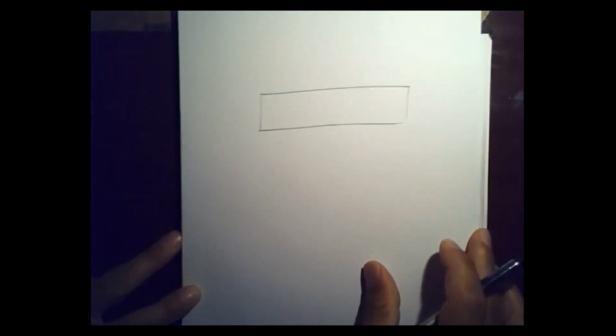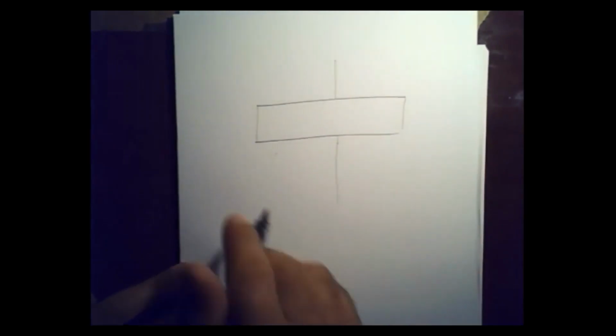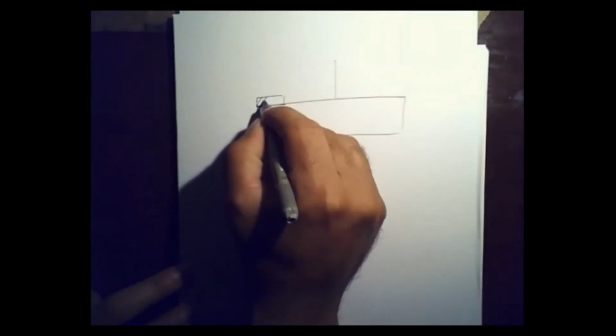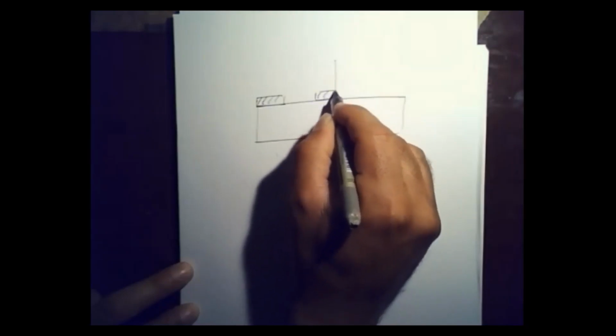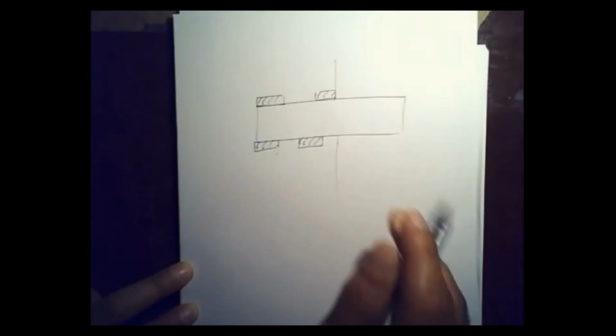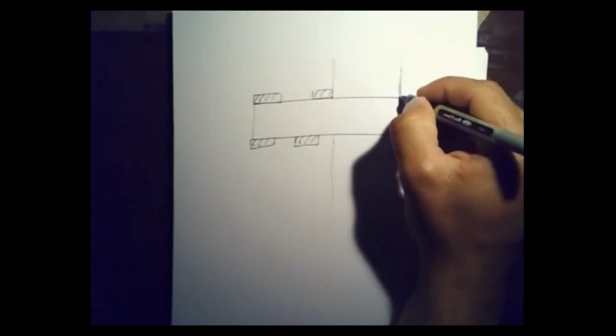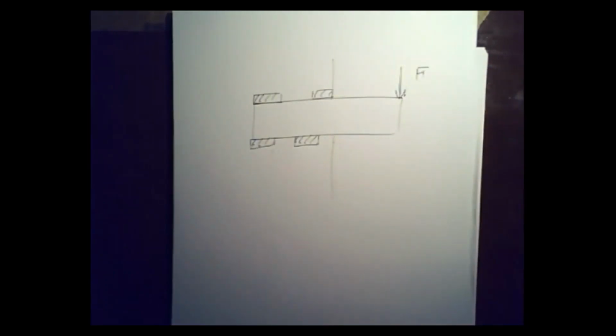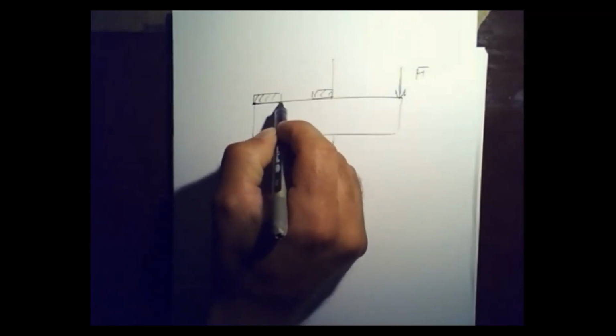All right, so in the case of a torsional stress applied on a weld, let's say you have a beam, and that beam is connected on a wall, and you have welding over here, and you also have some weld over here. And let me just make it like that, and let's put some weld over here, right? And let's say this is going to be your force. How do you find the shear stresses, let's say, on this point, or this point?